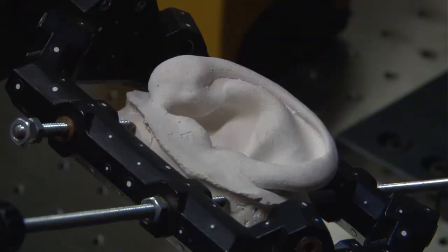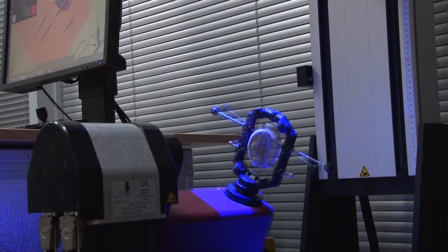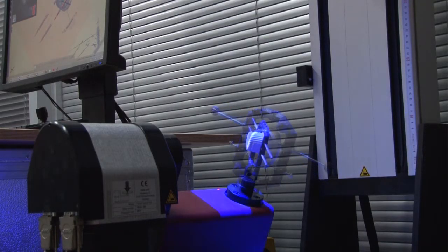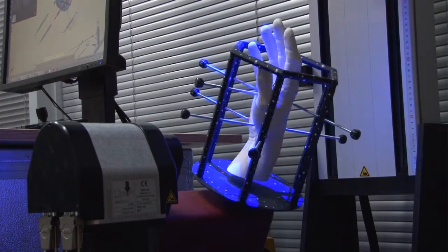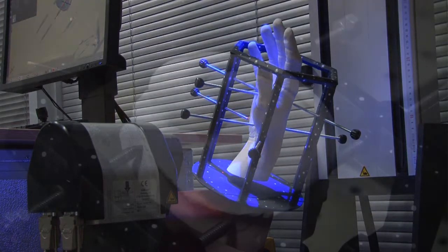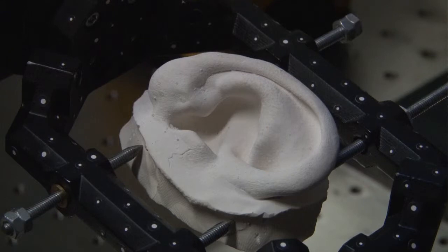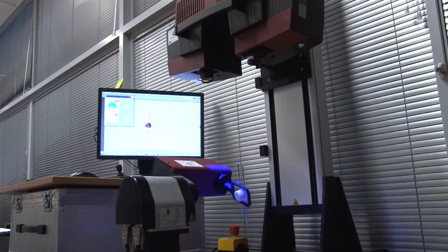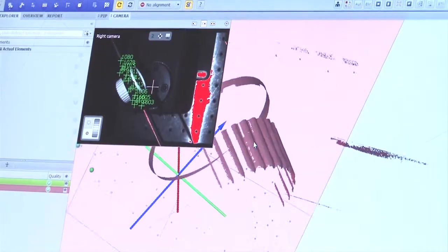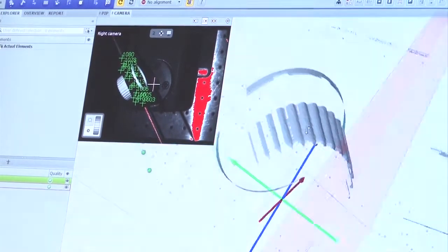For small part digitalization, we use a rotating platform and tripods with a vertical movement, to which we attach the scanner's head. Then we attach the measured parts to special frames, which have pre-measured reference points on them. These points ensure that there is no need to sequence the individual scans, thus making the whole measuring process much faster. When measuring a batch of the same parts, we use scripts, which ensure the automation of the whole process.